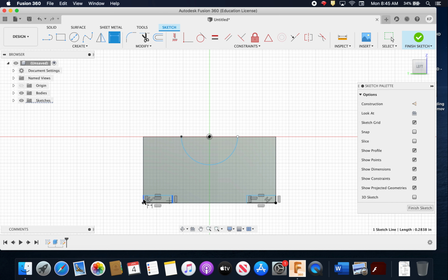So our first dimension is the width, and we are going to make this 0.75, and you'll see the other one adjust automatically. And the same thing should happen here when we go with our thickness, and I want to do half of the total thickness of that bottom part, which was 5/8. So what you can do, if you don't know the decimal, so if you want half of 5/8, which is 5/16, you can just do 5/16, and it recognizes fractions as well.